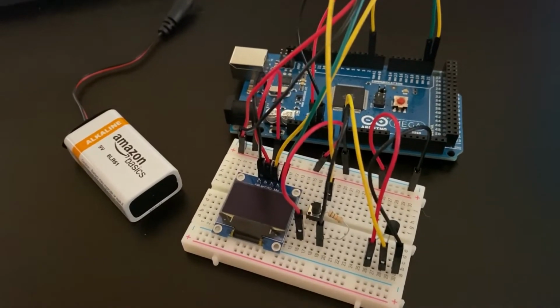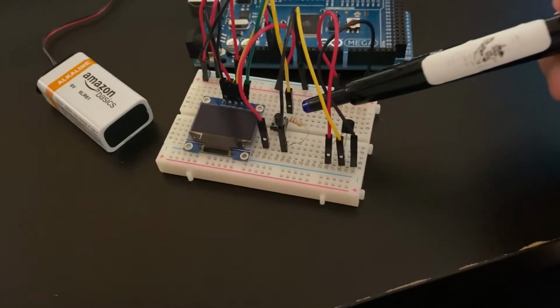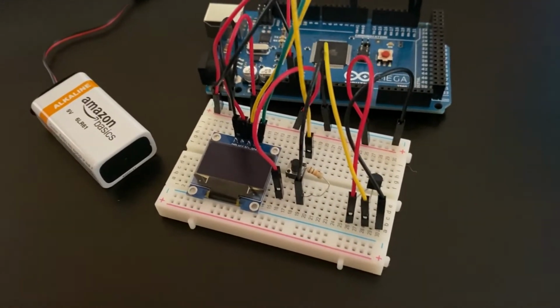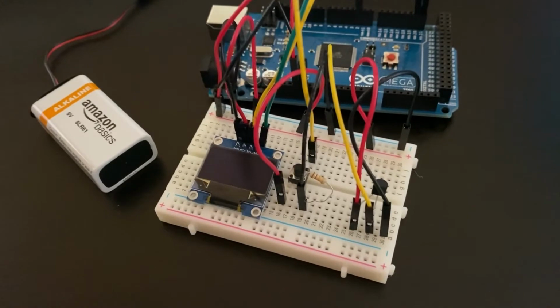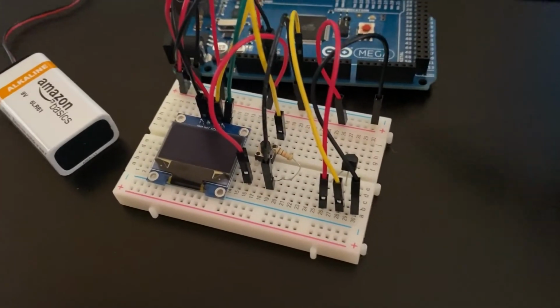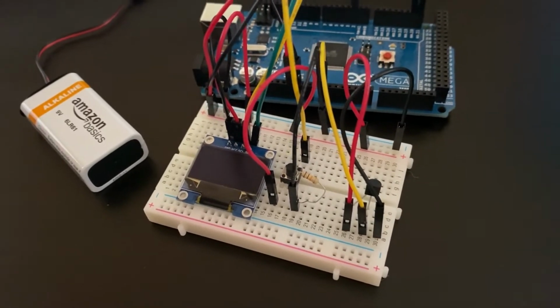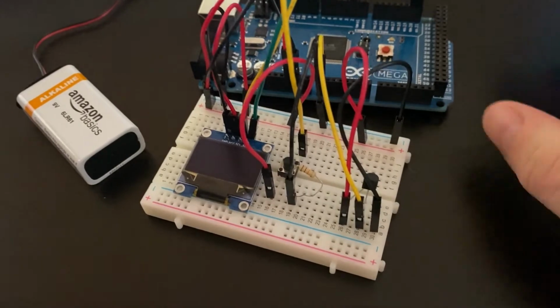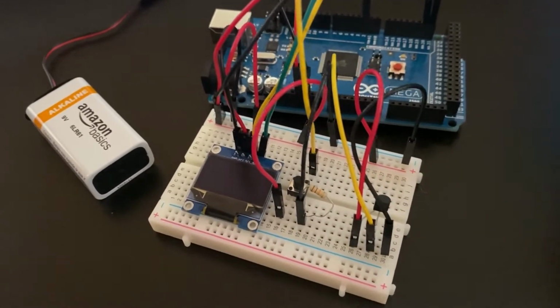My design was a round robin with interrupt architecture, and in this system I basically have two interrupts. One is the falling edge detection on the push button and the other is the timer interrupt that triggers every second. That's done through some software configuration, and it controls Timer 1 that's on board the Arduino. The logic for responding to these events is all controlled via software that's developed in the Arduino Sketch IDE.